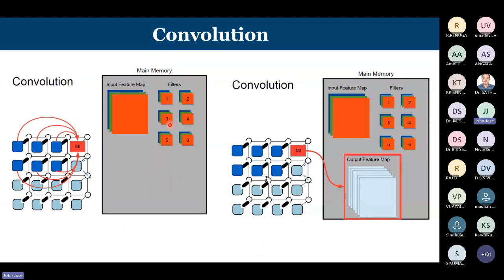What you have to see is the logical diagram that you have seen. There are chips from NVIDIA, and chips from processor manufacturing companies in the semiconductor field, which will generate this. These are not your conventional microprocessors. A microprocessor can do a lot of operations: adding, subtraction, square root. These are only capable of performing multiplication and adding, because the base of a neural network is multiplication and adding. That's a convolution operation. So can I arrange a sequence of multipliers, and then have some control circuitry which will supply these multipliers with the appropriate multiplicand and multiplier? The name accelerator means it's a circuit something similar to this.